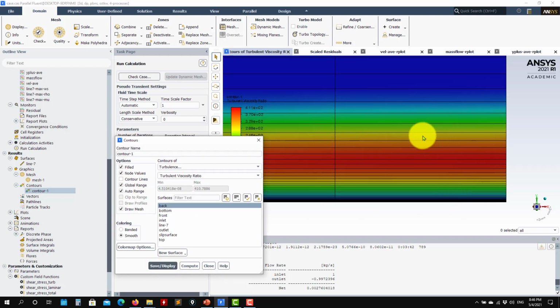So the criterion is that the transition, see here in these peaks, should be smooth. So for instance, you do your mesh and you have unstructured cells. And let me show you that if you go, for instance, in this cell here to a cell like this, see that you have this cell center. Okay, a little bit. You have this cell center here, and then you go to this one. So see that you have this jump here. Remember that you are computing gradients and you are interpolating this. So this will add a lot of numerical diffusion. Okay, so always be careful of this.